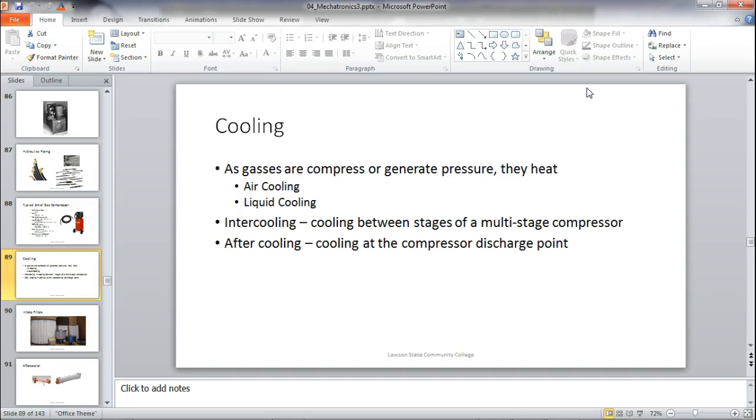What do we use to open? If you've got electric locks on your car, what do they use? Do they use a solenoid or do they use a motor? They use a motor because the solenoid would let you unlock it, but what you couldn't do, you couldn't lock it unless they come up with some method. So it's a motor in there. It's a locked motor, but it doesn't have a limited stroke, so we limit the stroke outside of it, right? You understand? So there's some type of switch that when the thing unlocks, it cuts the motor off. And don't let it come up again until you take it back down. Does that make sense?